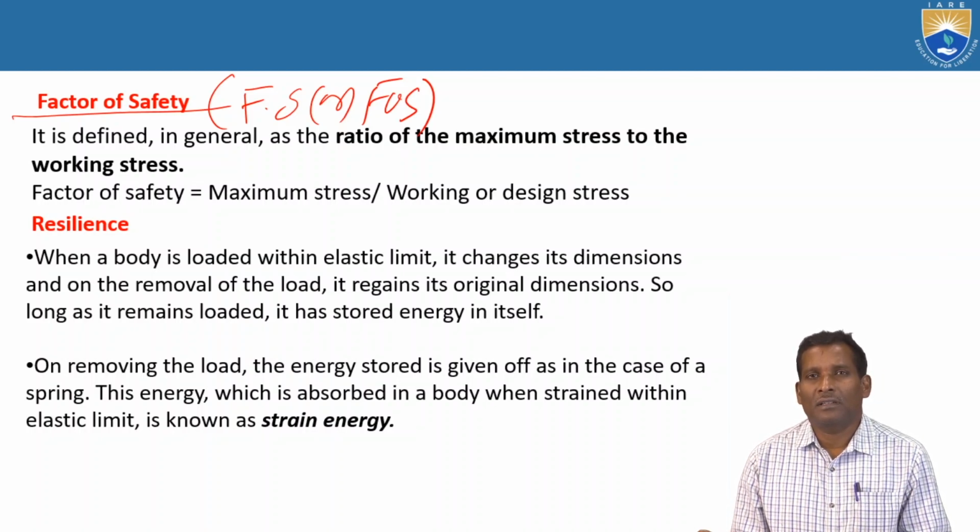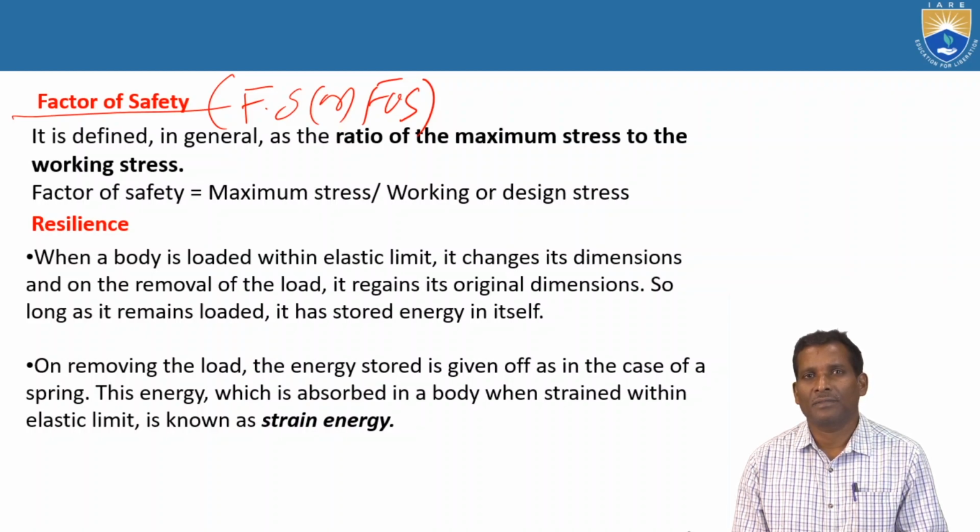It is the ratio of maximum stress to the working stress or design stress. The factor of safety is used in design of machine elements to avoid failures. This factor of safety is used for safe design only.